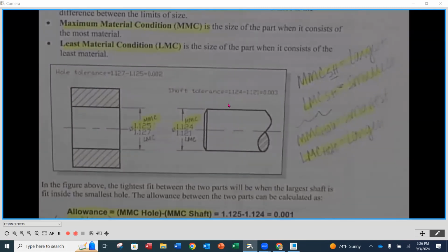When a drill wears, we think that the drill is getting smaller, right? And you would think it would make a smaller hole. That is not the case. Because of the dullness that's created, the chips in there are getting larger, and they're actually going to be kind of boring that hole out along with it. And the hole gets larger as that drill dulls.